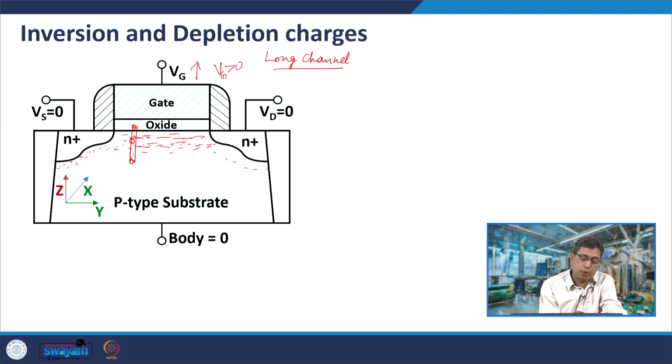So, what would be the surface integral of electric field along the vertical surface of the cylinder? It would be 0. Only the surface integral of electric field in the top lid must be considered. In the bottom lid, the surface integral will come out to be 0, because the electric field itself is 0, it is a neutral P region.